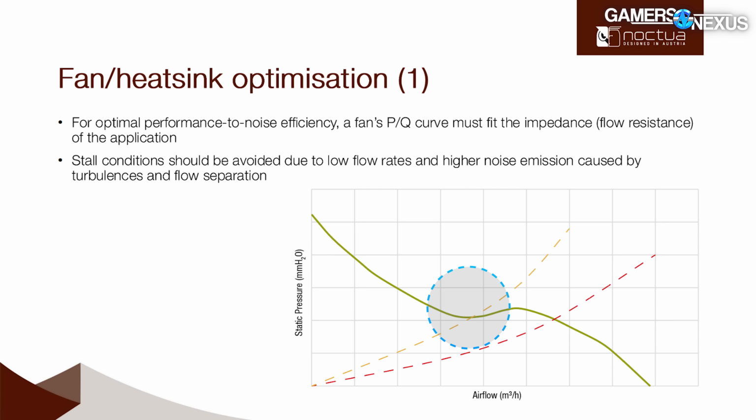And you basically never want to push too close to that dipping region, because as we've discussed before, once the fan stalls, it pushes less air through your application, and flow becomes extremely turbulent. So it will sound not as nice. It will be measurable in SPL, and it will be not as pleasant in tone.